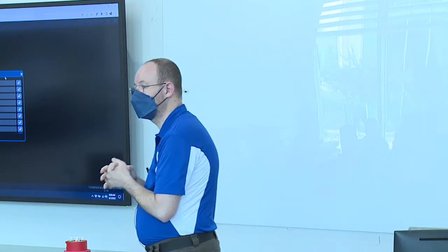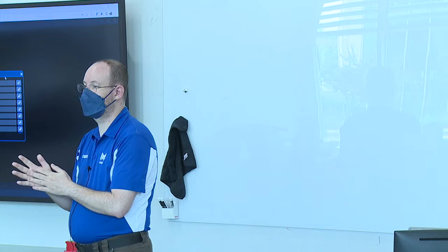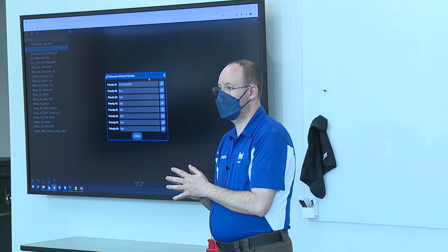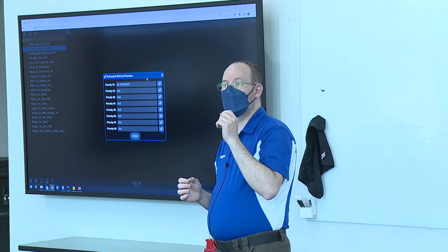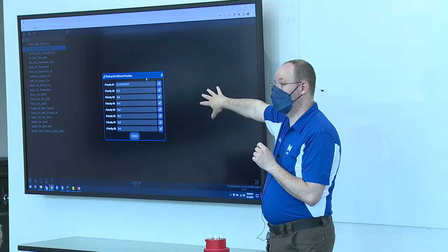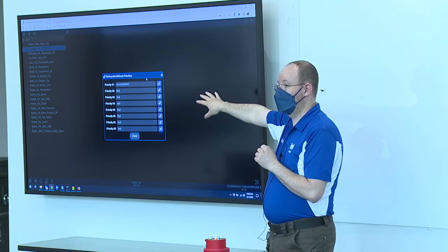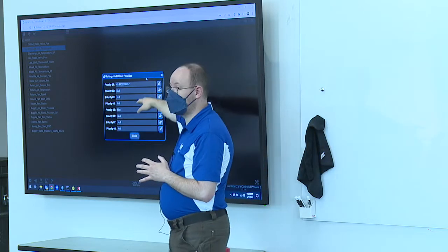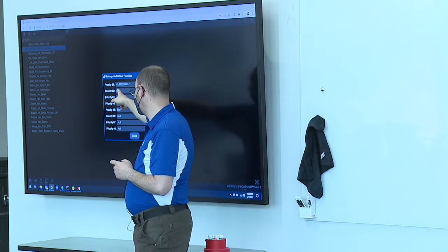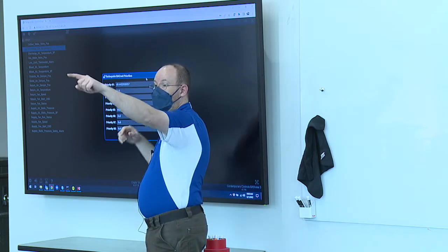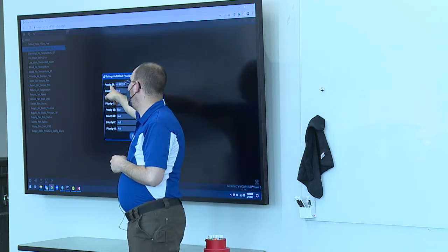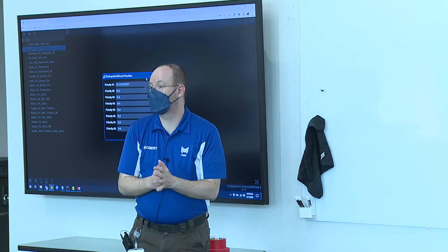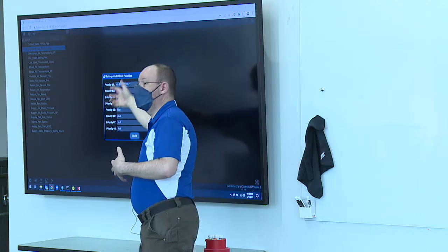Ted: So when you set up these different points, was there automatically a default priority set up for that particular item once you set it up? On the BAS view side? No, these priorities all exist. So it is reading from my air handler back there. It is checking the value at priority 1, 2, 3, 4. So it pulled it in. Correct, this is literally pulled data.